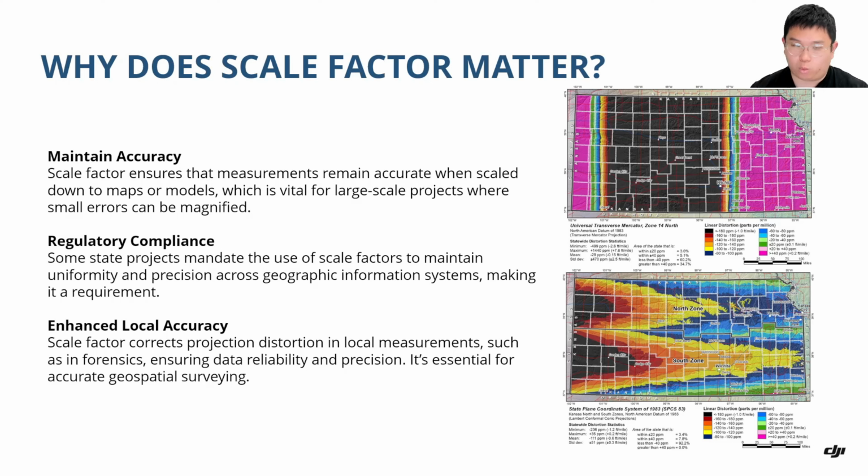Okay, now let's talk about why does the scale factor matter. First of all, it would help you maintain the accuracy across the entire project. If you have a large project, especially cross-state projects, applying scale factor effectively would make sure your measurement is accurate. And sometimes, due to the regulatory compliance, it is a requirement for certain projects to apply a given scale factor to your measurement, so all the measurements are comparable.